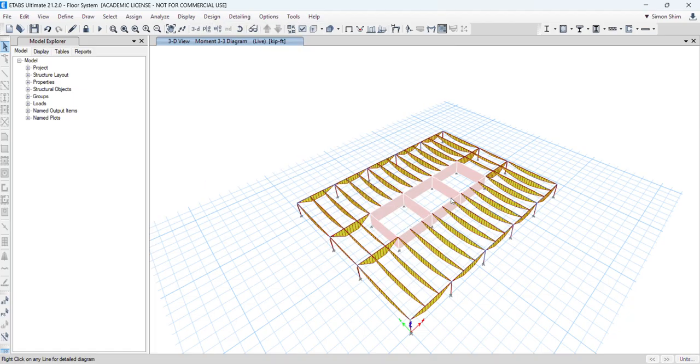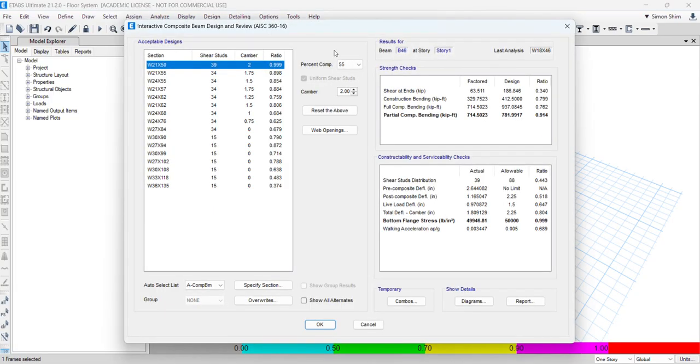Vertical, yeah, right. And right click here, you should look at the beam deflection here. So for the live load beam deflection, because it's composite action under the permanent condition, your live load deflection will be 0.97 inches instead of 4.6.